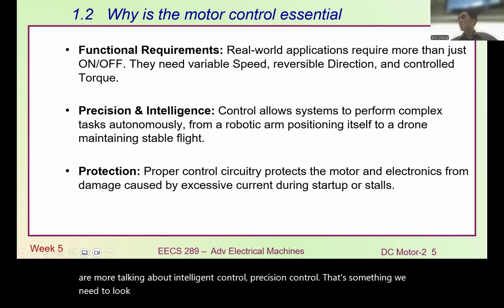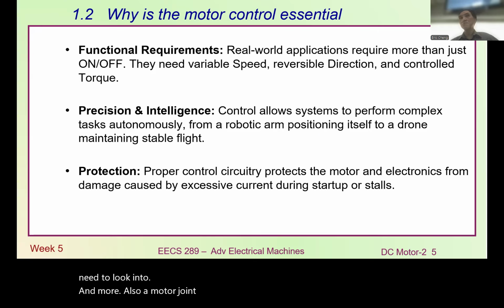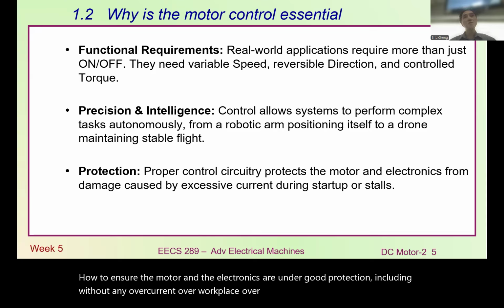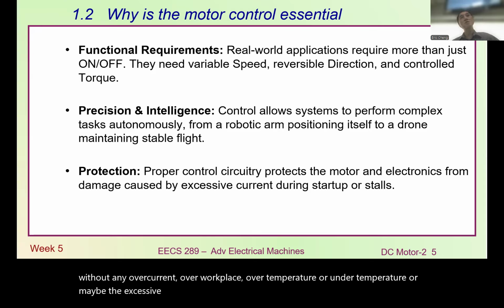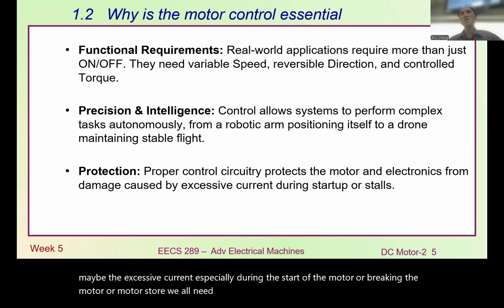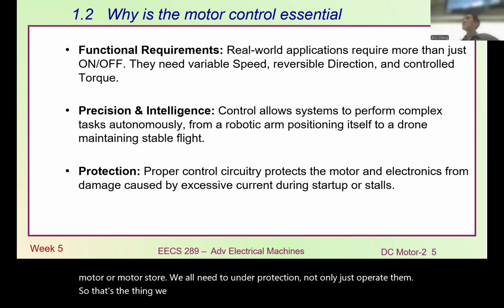And a motor drive system is mainly about protection, how to ensure the motor and the electronics are under good protection, so that we don't have any overcurrent, overvoltage, over temperature or under temperature, or excessive current, especially during the start of the motor, braking the motor, or motor stall. We all need protection, not just operation. That's the performance we need from the motor drive system.